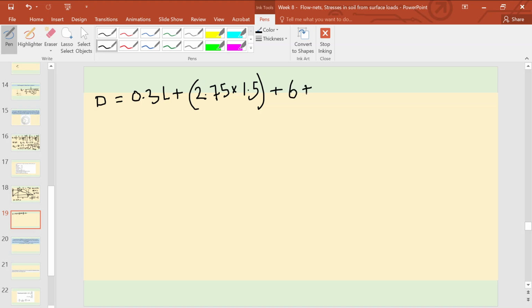Now on the downstream side we take the entire thing, the height multiplied by the slope, because in the downstream side there is no water, so no need of freeboard counting. So height multiplied by the slope, that is 2.5. Now we have taken the entire downstream side, we just subtract the length of the drainage blanket, 110. Now what is the value of L?